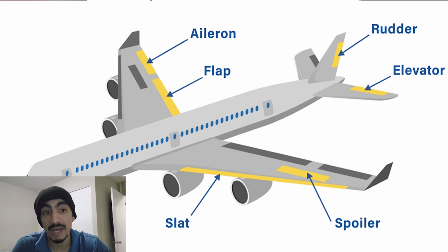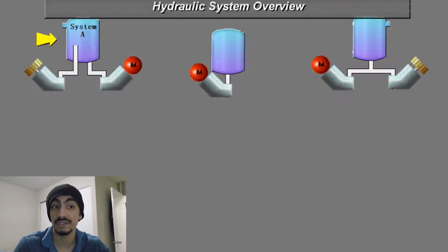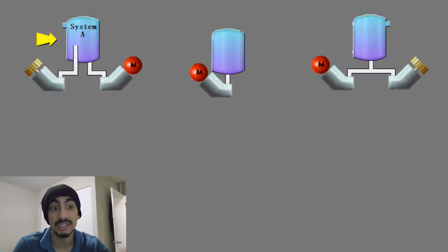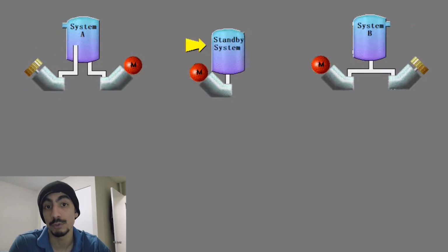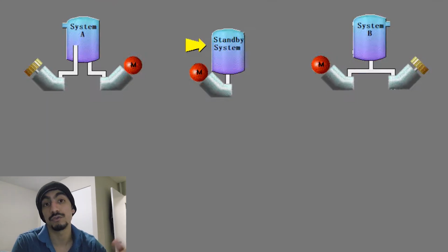So modern aircraft typically have multiple independent hydraulic systems. That means if one line gets punctured or loses pressure, the other ones are still intact and can be used. So let's say there was debris or a mechanical malfunction, and one hydraulic line gets damaged, you still have another system that can keep those surfaces operational. It's like having 2 or 3 separate safety nets. If one tears, you've got another to catch you.